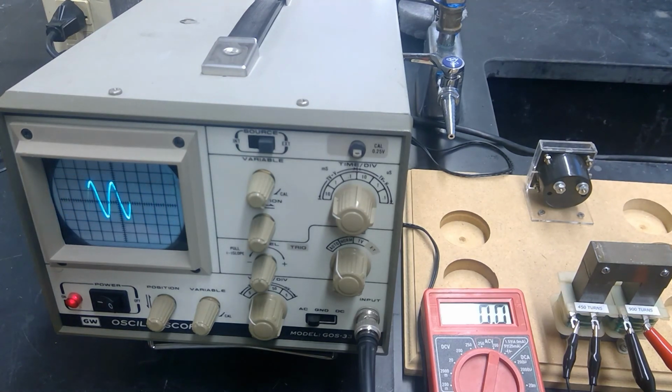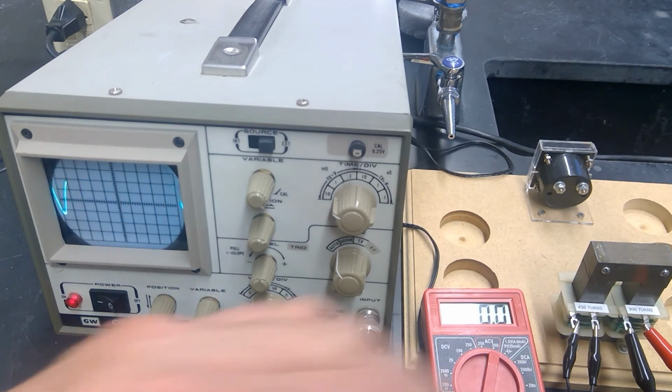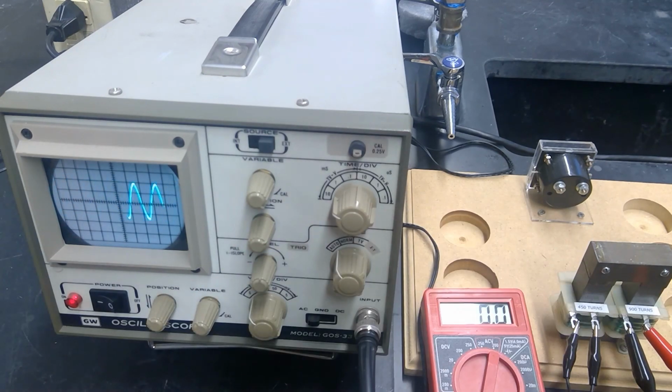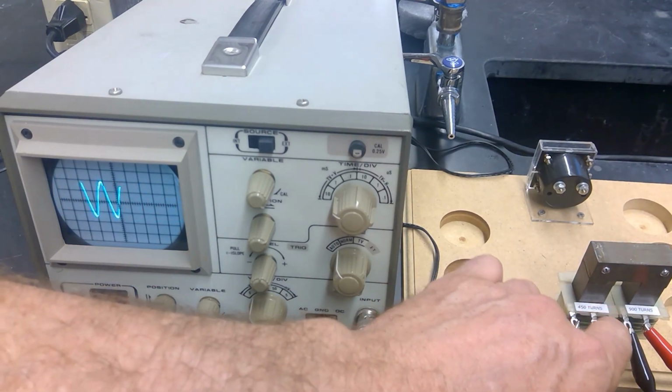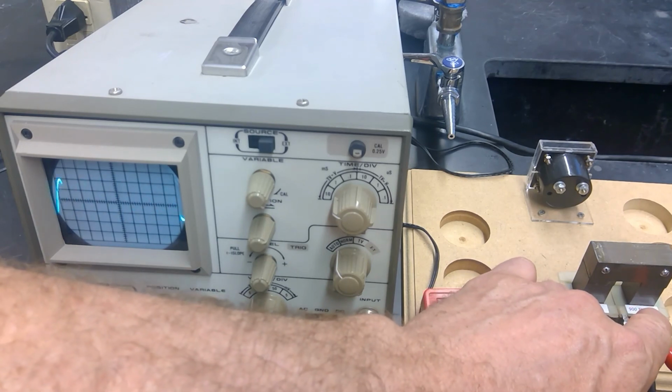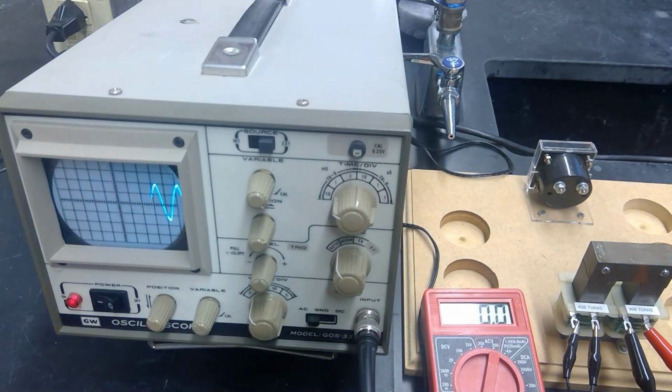In most cases, we are trying to step up voltage with an inverter. So in all of the inverters that we are working with at CSAS, whether it is one of those big inverters for the standalone or the microgrid inverters for the grid tie, we have these transformers embedded in the device that have a primary and a secondary, with the secondary having considerably more windings to try to move that voltage up to either 120 in the case of the standalone or 240 in the case of the grid tie.